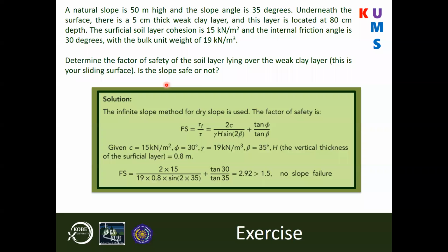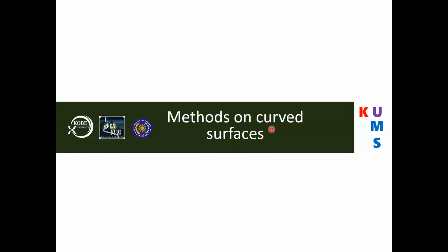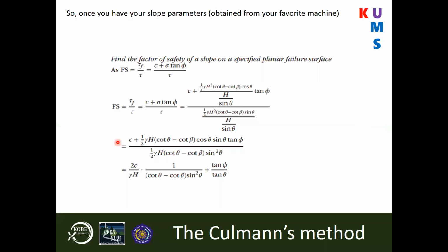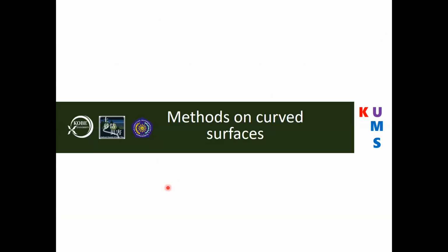And this is for two parallel slopes. So you have the slope and underneath the sliding plane is the same. So we have our beta angle, which is this angle. And then for the second one, when we have a wedge, we have to get rid of that extra bit of movement to get our angle, and that's what you can use.